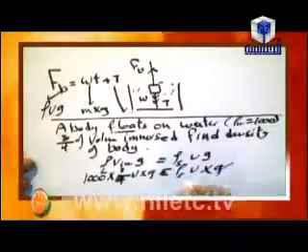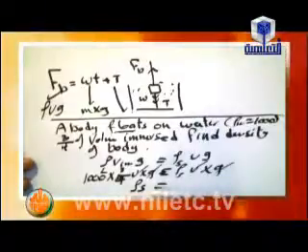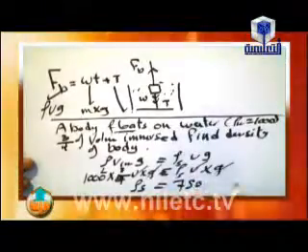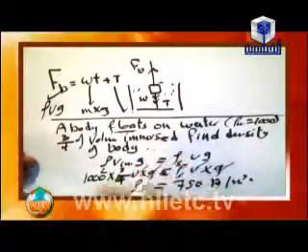We can cancel g and V. So rho solid is equal to 750 kilogram per meter cube. This is in case of floating. So for the floating body, the buoyant force is equal to the weight of the liquid displaced by the immersed part. But in case of wholly immersed, the buoyant force is equal to the weight of the liquid displaced by the whole body.